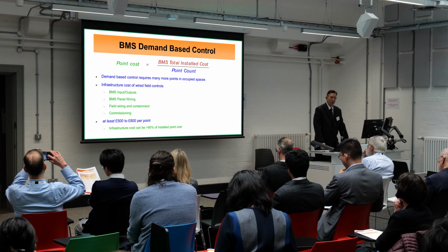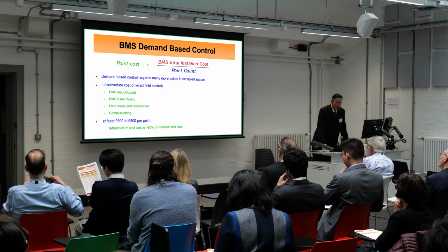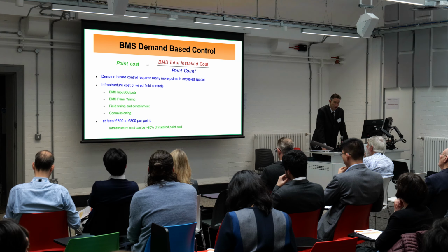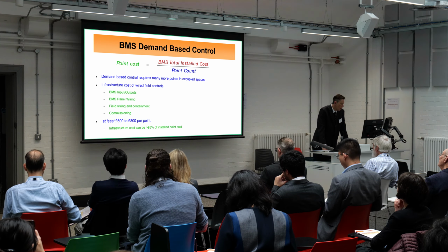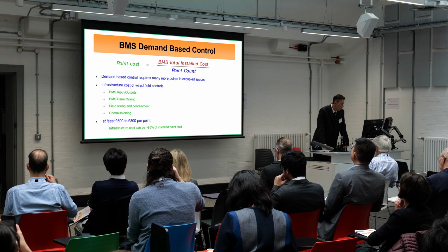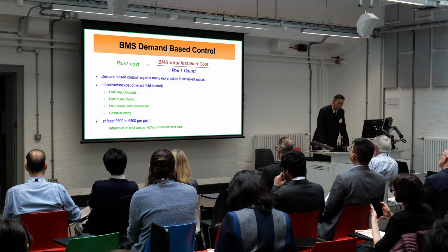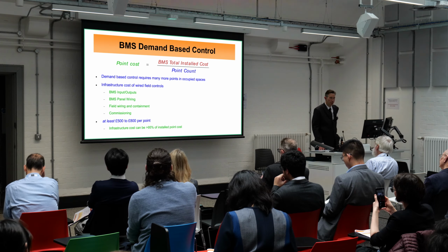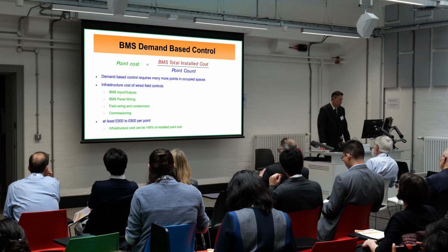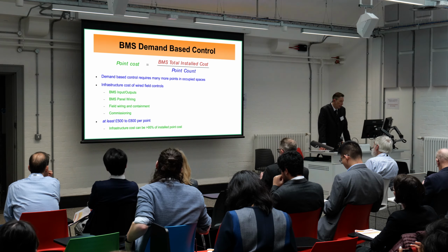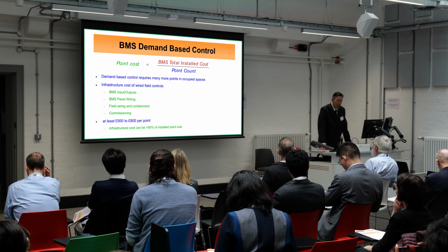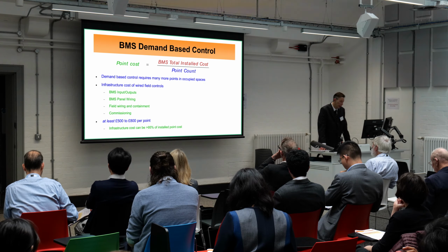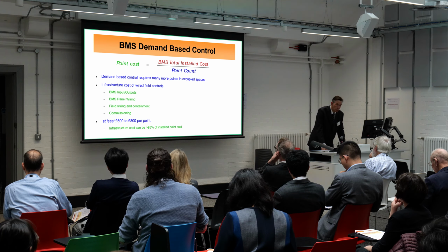Of course, all of that information is not free. So putting in sensors has a cost associated with it, and obviously any energy savings we achieve needs to be justifiable from the capital cost. So in BMS terms, there is a very common metric, which I'm sure some of you are familiar with, the point count, which is the number of inputs and outputs in the control system. If we look at the cost of that point count, how much it costs for the hardware and the installation, and divide it by the point count, we get a notional value, which is the point cost.